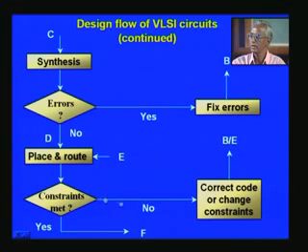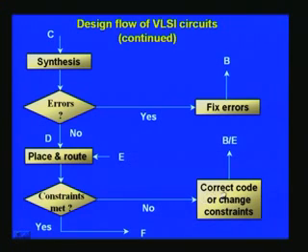Even then I think you will have to get rid of warnings etc. before you go to the next step. Otherwise, if you are particular about 100 megahertz operation, then you will have to identify where you can introduce additional pipelines etc. so as to improve the speed of operation, and for all that you need to correct your code. So once again you have to go all the way back to recompiling, right? And if it is merely a constraint on speed, you don't have to go there, and you can straight away tone it down to the lower frequency that you want and then proceed.